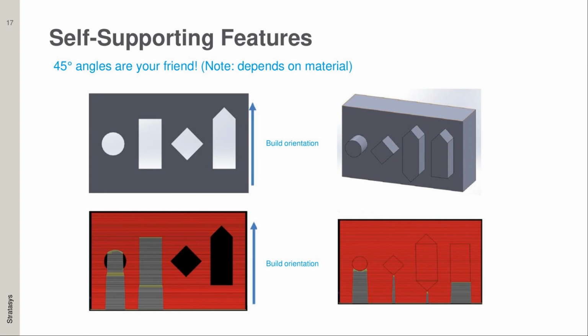Now, if you have an extruded part, you'll need to be mindful of that because you'll have a part that's coming out of the printer, not cutting into a hole. So you will need to design not only a 45-degree angle in one axis, but also the other axis to eliminate the need for support material. But in general, if you have a hole or a feature like that, I would recommend printing it with a diamond and then drilling it out later so that you can save cost and save time printing the part.